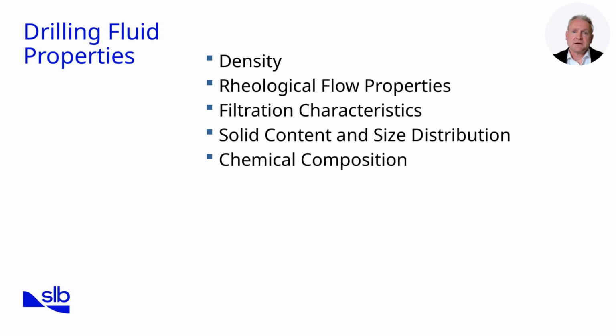Third is filtration characteristics. These control the invasion of fluid into formations. Poor filtration can lead to filter cake buildup, differential sticking, and poor hole cleaning. Fourth is the solids content and size distribution. Excessive or poorly graded solids increase fluid density and viscosity, reducing cleaning efficiency. Proper solids control equipment is necessary to maintain desirable levels. Fifth is chemical composition. This impacts the stability of clay formations and reactivity with drilled cuttings. Inhibitive muds help prevent the dispersion of shale cuttings, which would otherwise complicate transport.